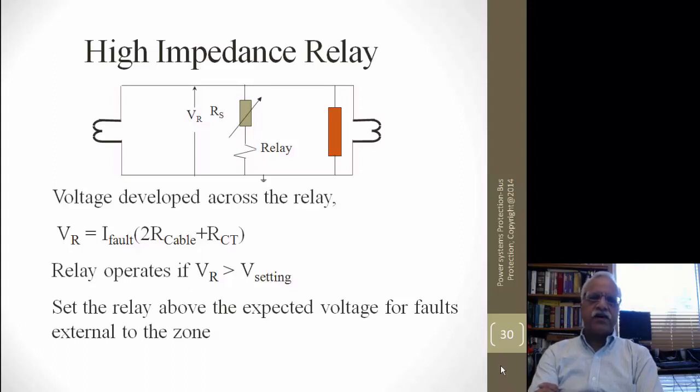We talked about various bus arrangements, and then we also talked about the CT polarity and zones of protection. And we mentioned that under normal conditions, the sum of all the currents may not be zero on the secondary side of the CT connection in a bus protection, even though on the primary side the sum should be equal to zero. This is due to CT saturation. That could be due to the DC offsets in the currents, and also the inaccuracies produce some operating current.